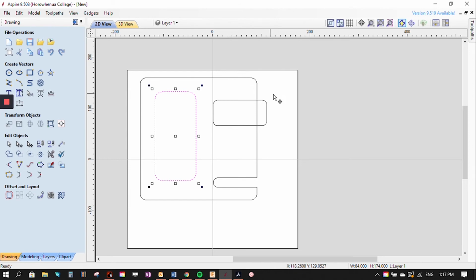Okay, another good thing to know regarding how to position things. I showed you how to position things using a rectangle tool earlier. Another way to do things is to use the guides. To create a guide, you click on this ruler space on the left here, hold down and drag it across, and you can see the little numbers that pop up as you go across, right?